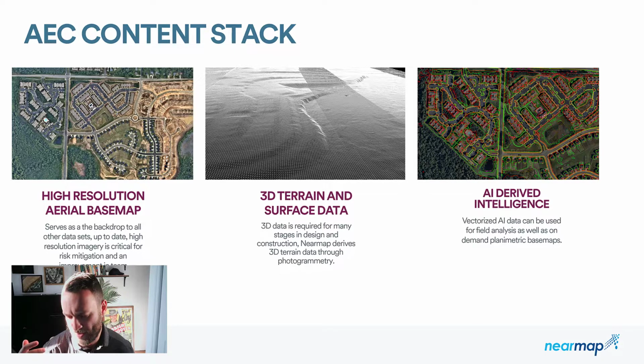The 3D data set is critical to have something that's up to date. As you know, a lot of design decisions can be make or break from that third dimension, right? So a highway that's being proposed on a horizontal plane might work great, but once you start applying the profile analysis, that design might no longer work. As well as mitigating cost.